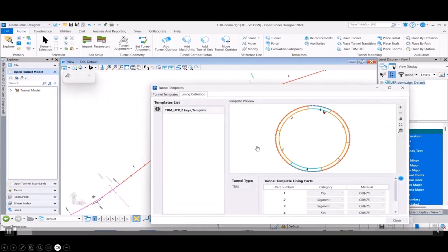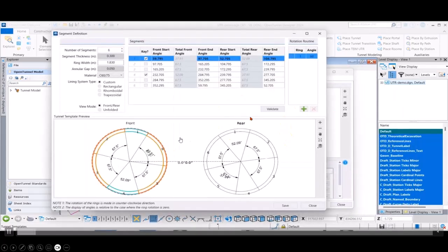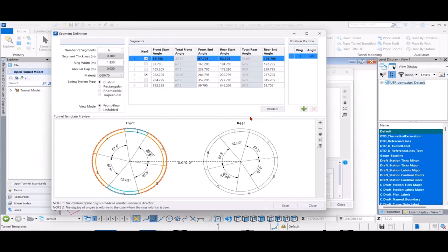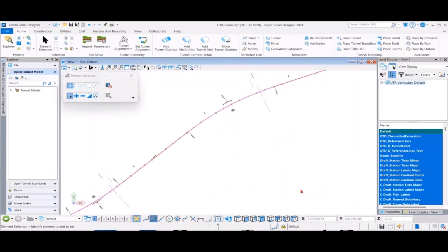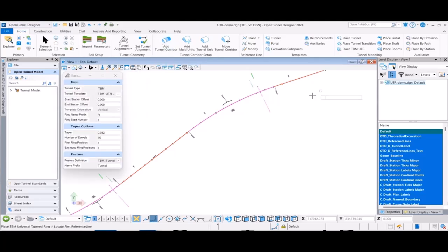So after you place the tunnel, these are the rings that need to be rotated along the corridor itself. So that complex calculations are done automatically now by the software and can present it to you in a report, and also in what extended layout, right? So it's being enhancement required a lot of geometry calculations right there that now these are saved by the software itself. So as we generate the tunnel now, all these rings will be automatically calculated and their placement of that.